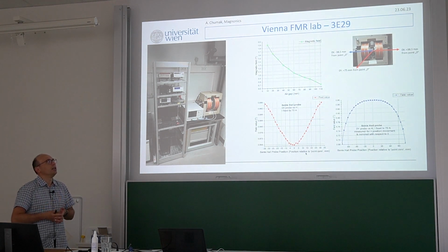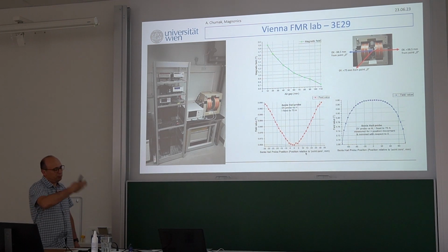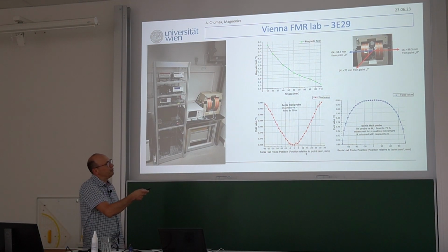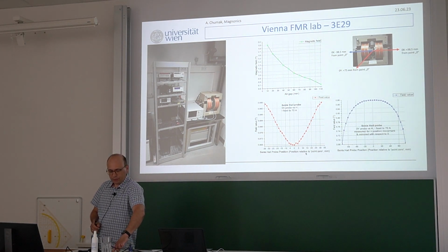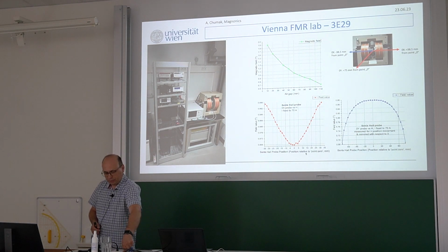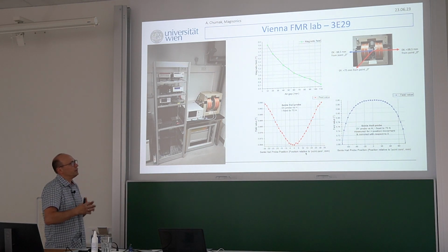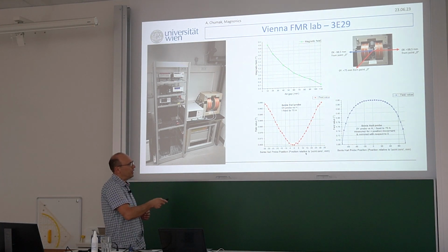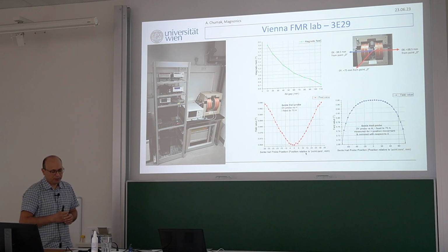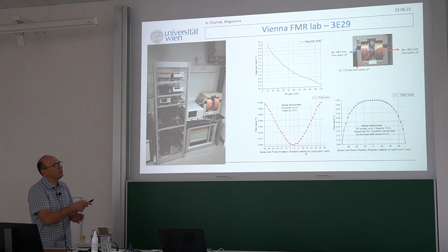Sometimes it's more critical, sometimes less critical, and usually what we do is perform a very simple calibration: you put a Hall probe in and fix it with some screws, step motors or so, and then you can measure the magnetic field versus coordinate in all 3 axes. And principally, the more uniform the field you have in your magnet, the better.